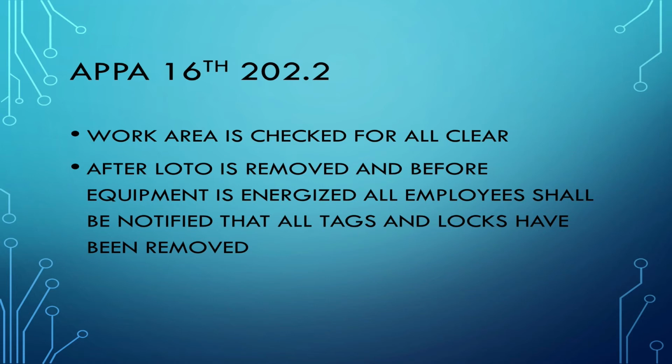So a lot of different sequences could come through. You should have the breaker tagged if this is the case. You should have the open point tagged as well, and then you would release those in the opposite order as you got them. So it's fairly simple. Sometimes it's a little time consuming, and sometimes we think it's not necessary.